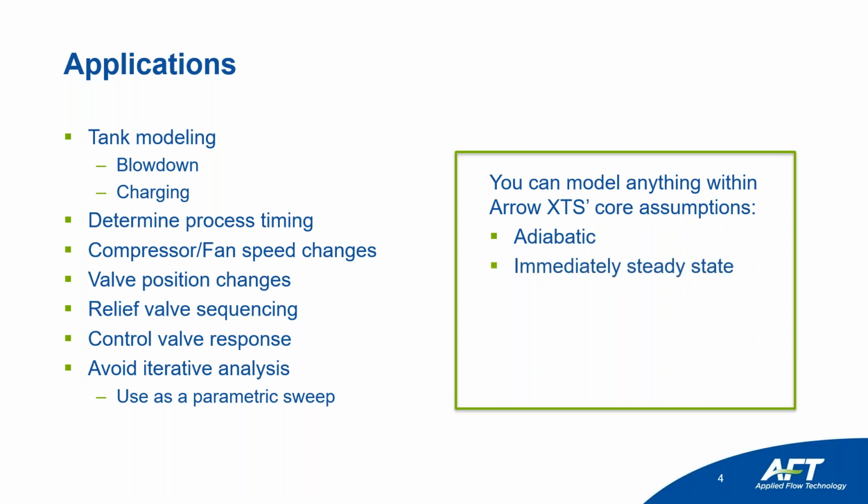The next one is something that we've touched on pretty frequently, which is that because we're modeling the transient analysis as a series of steady state snapshots, anytime that you see a change over time, it's going to immediately reach a new steady state. So if we take our valve and go from 100% open to 100% closed in a single time step, then we have to be okay that it's immediately approaching that new steady state. You're not going to see the reflection of pressure waves that you might in a more complex tool like AFT Impulse or AFT xStream. Again, this assumption will be okay for a lot of different applications.